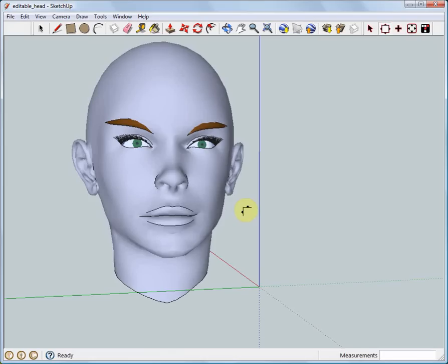In Tgi3D plugin for SketchUp, surfaces can be made to follow curves. Tgi3D Bezier curves function as control curves when they are woven as a part of a mesh surface. By editing those curves and subsequently smoothing the associated surfaces, you can easily reshape complex surfaces with a high degree of control.